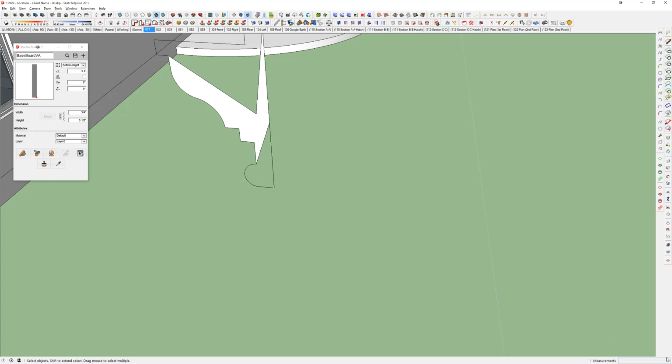And if you notice down here on the bottom right, where you always do your measurements and inputting all that kind of stuff, if I hit my F12, you'll see it changes to field of view. SketchUp default is 35 degrees, and that seems to work really well for exterior shots. When we get into interiors, we'll talk more about that, because I actually find that 60 degrees works much better for interior shots because you get a much wider view.